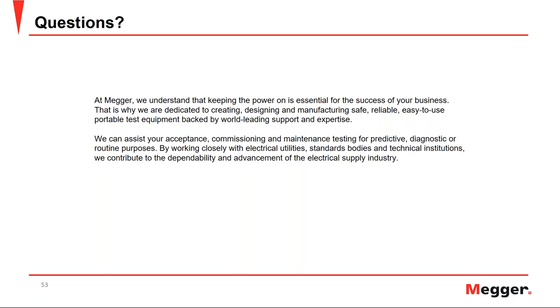However, as we saw during the presentation, the power factor testing has some limitations. When you have a power factor result that is increased, or we detect a trending issue, or the values are increasing in the trend, then the outcome is always investigate. So we always have to investigate further.